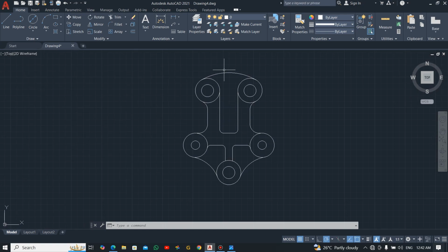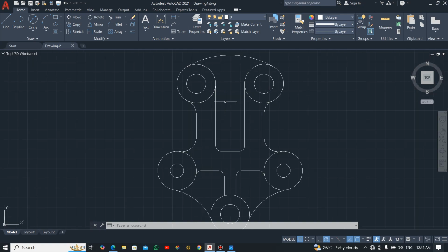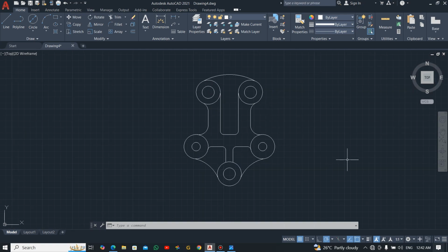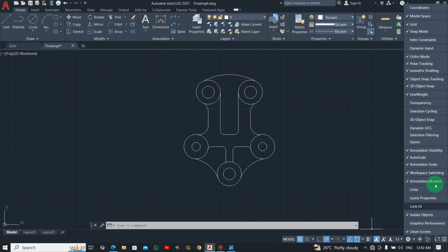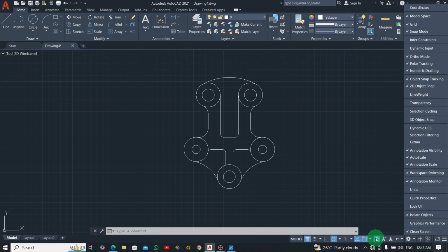If you want to make the line a little bit thicker and nicer, just go to this and select line width. Go to the notification and select line width. Now if you are not seeing it here, you have to come to your customization tab here, click on it, and then you look for line width. I think mine is somewhere here. Line width is here, is it. See, when you uncheck it, it will not be here. You won't see it anywhere here.